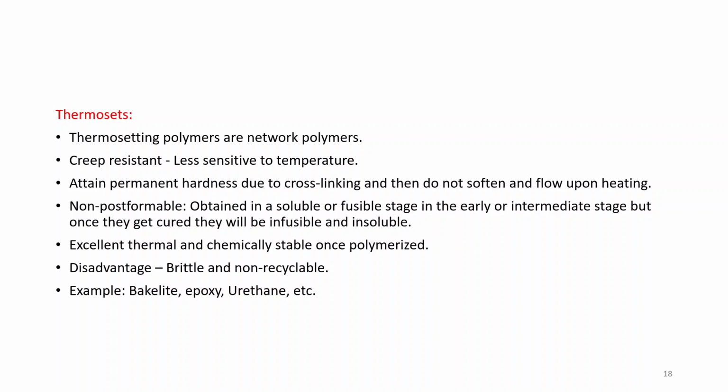And these are non-postformable, so these are obtained in a soluble or fusible stage in the early or intermediate stage, but once they get cured they will be infusible and insoluble, and they have excellent thermal and chemical stability once polymerized. The disadvantages include brittleness and non-recyclability. Other examples include Bakelite, epoxy and urethane, etc.